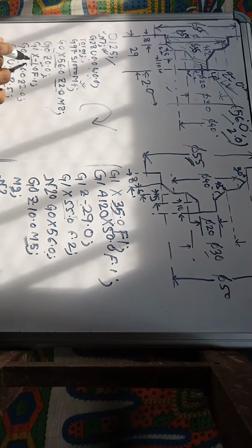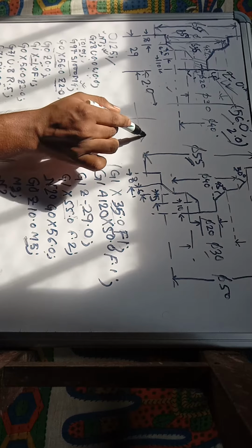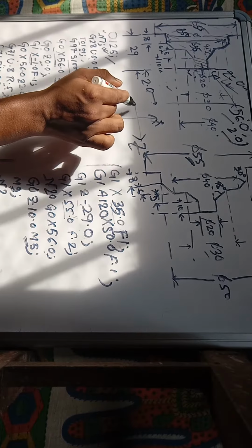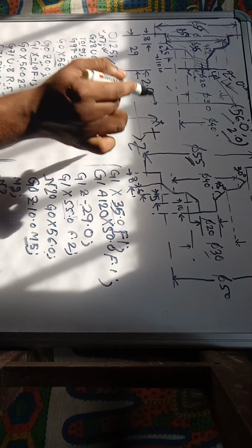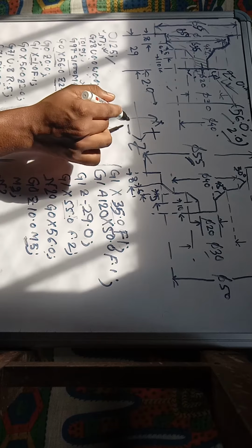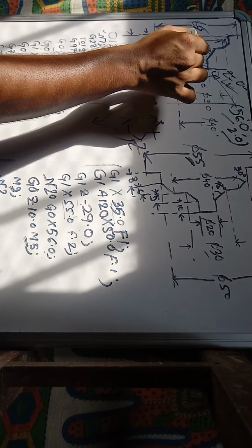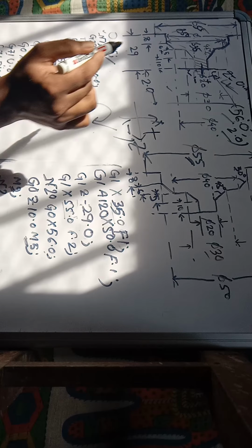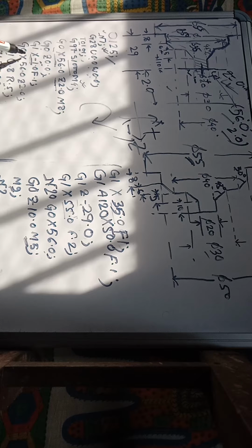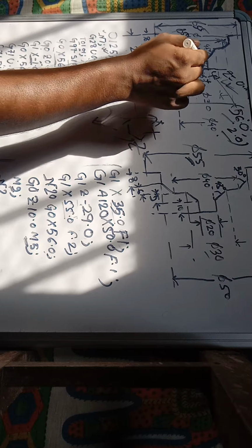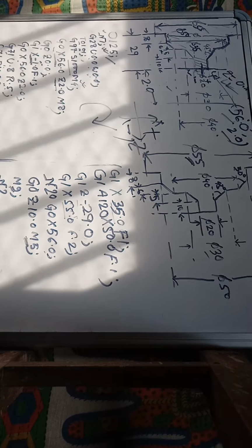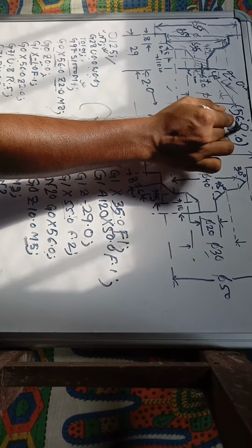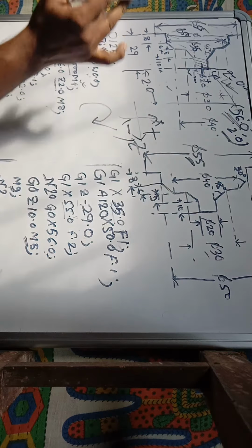Suppose there is a coordinate system with the Z axis and the X axis. Above the Z axis whatever you write is positive, and below this it is negative. So that is the center line: above it is plus, below it is negative. You will simply use X minus 1, so that it will clean the face easily. After the facing, it will move to this position, X56.0 and Z2.0.